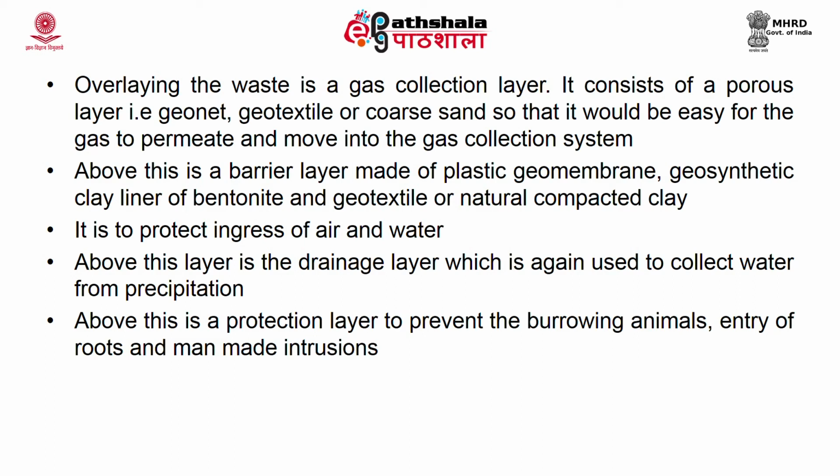Now, above this is the protection layer, which is used to protect the cover material or the lining material lining the top layer of the waste from burrowing animals, man-made intrusions and entry of roots. On top is the restoration layer. As I told you, on top, the fine 5 centimeter, you have to layer it with topsoil. This is done for growing some small plants. Even grasses can be used.